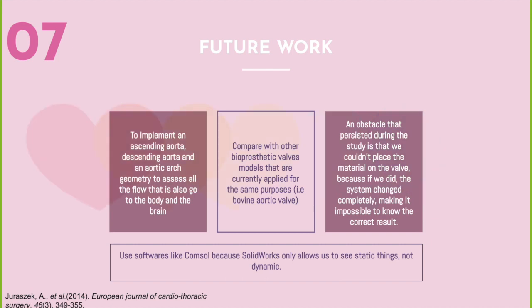This is a limitation that the software gives to us, so we could not put, for example, the tensile modulus, the tensile strength of the valve. So it might give us some results that might not be reliable, but since we compared the results of our shear stresses, our pressure, and our flow pattern, we could assess that actually our simulation is good.